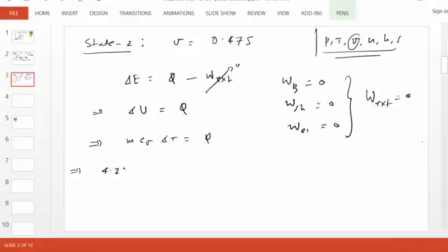If we substitute the values, m is 4.21. C_v for air is 0.718. Again, the value would usually be given, or you can go to the PG model, the PG table, and obtain the value directly. So this is a material property, it will be given to you. And delta T equals T2 minus T1, obviously. And Q is given. Q is 800. And T1 is given, 298.